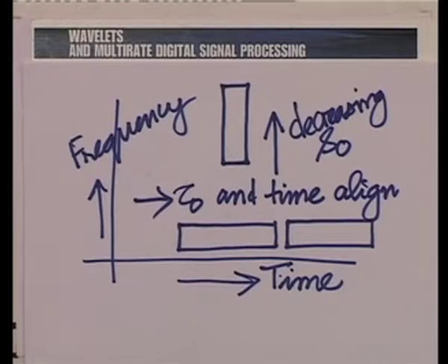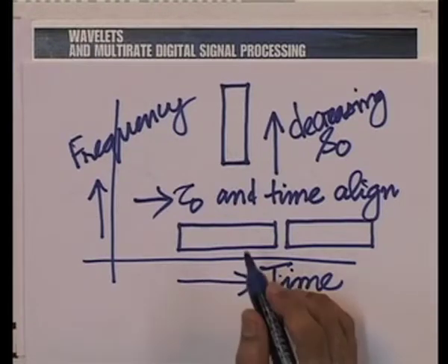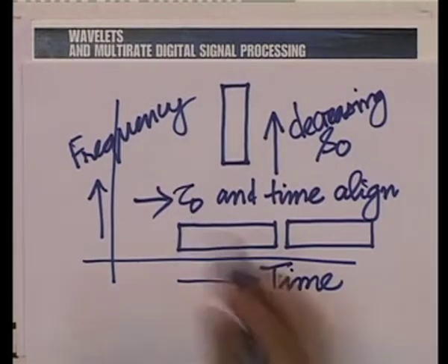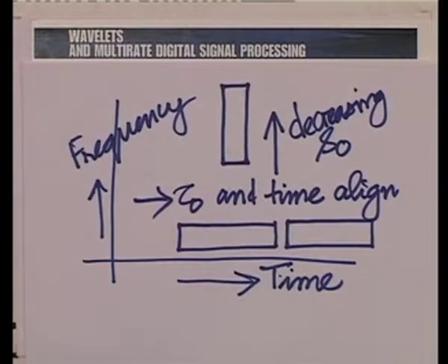Now, with this little background, we see there is a bit of asymmetry. Tau naught is okay, and therefore, we will allow tau naught to go as it is. We will take a cue from the short time Fourier transform. In the short time Fourier transform, we could just let tau naught go as it is in reconstruction. So, we will not worry about tau naught here either, but S naught poses a problem. So, we need to allow a weighting factor here when reconstructing, using the same principle of component multiplied by vector, and that weighting factor must depend upon S naught.